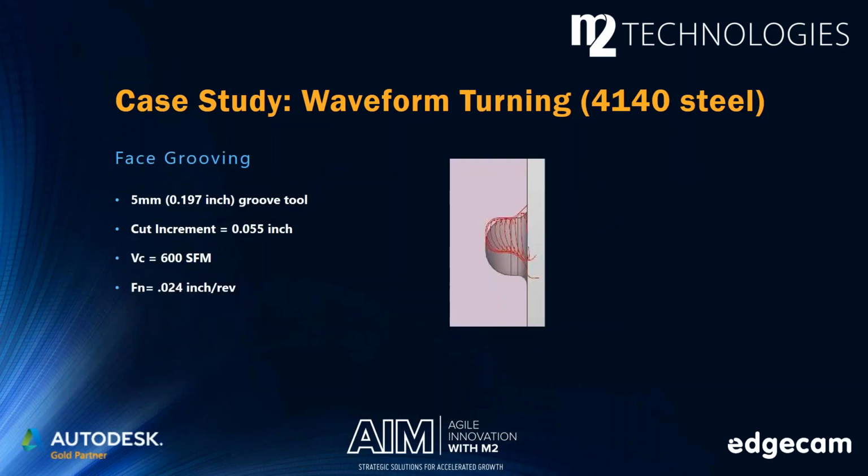Just a reminder of the face groove and the application we did there, again from the real world. In 4140, with a 5mm groove tool, 55 thousandths of an inch depth of cut at 600 surface feet, and with this one we were able to run up to 24 inches per rev for material removal. There, in turning centers, again, there's often a limit to how comfortable we are as users and machinists at how fast we want to run. Field experience will dictate that, but excellent performance benefits and much faster than traditional cutting methods with excellent performance and chip control.